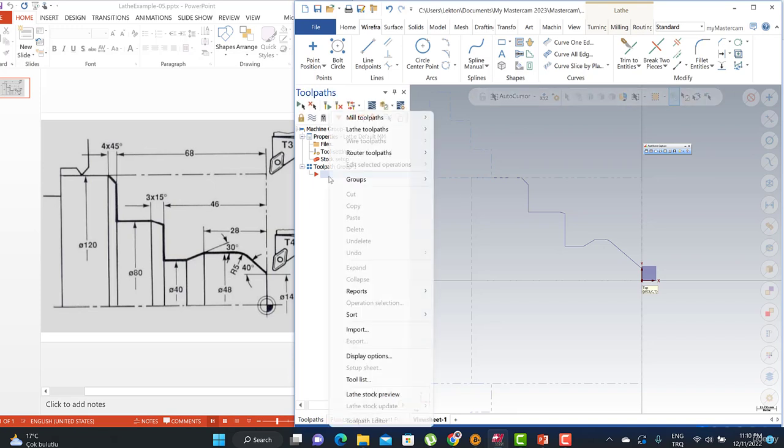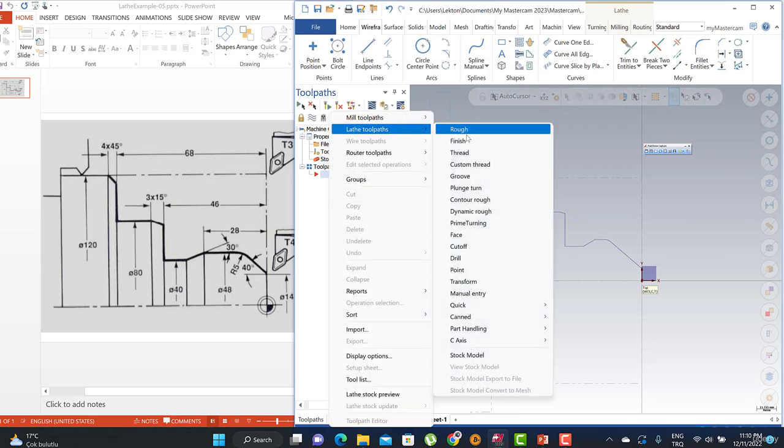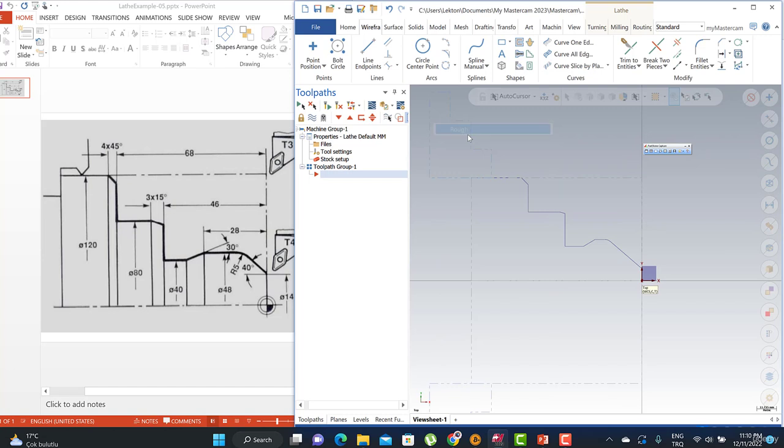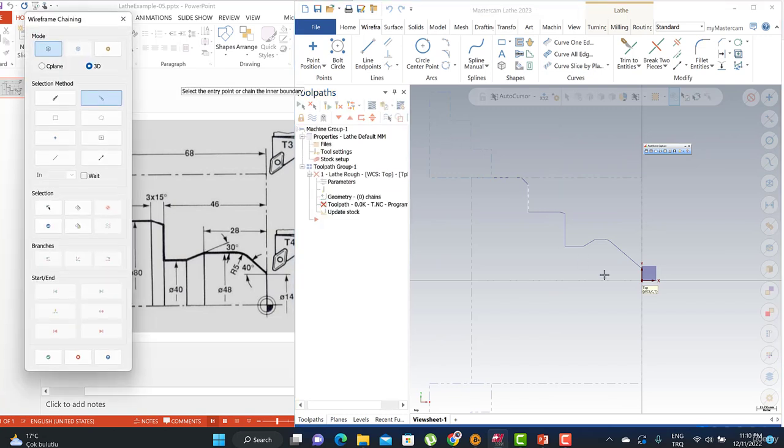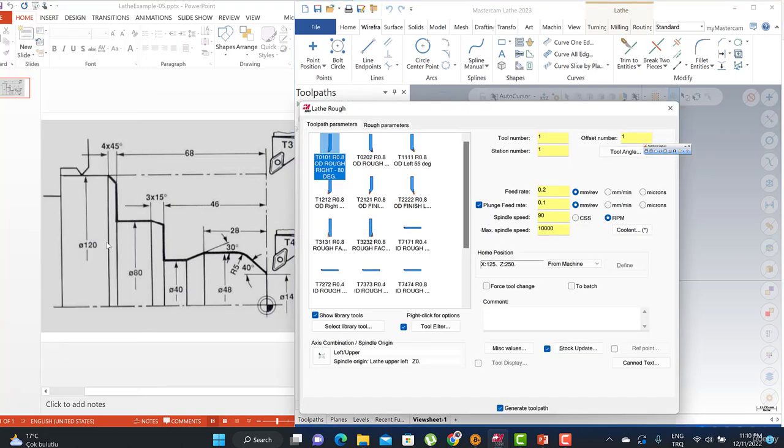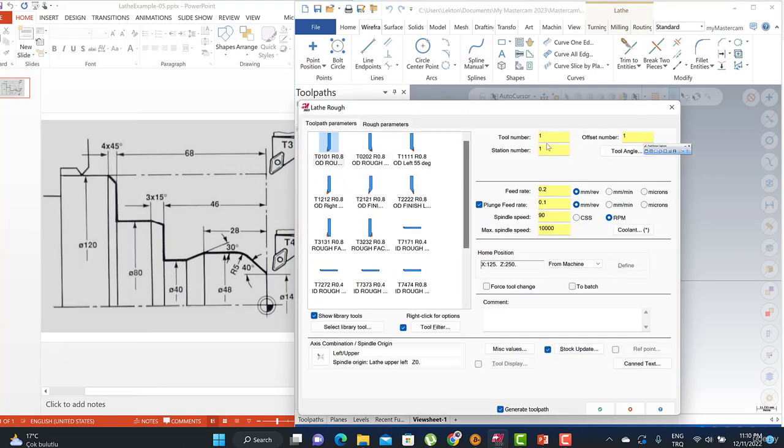After that, we can turn to the Lathe Toolpath. Maybe we can also use the rough parameters here, and we can start from here and reach here and click OK button. Okay, this is going to be my radius with the tool diameter 3 and feed rate and constant RPM. That part is not important because we are using the constant spindle speed.